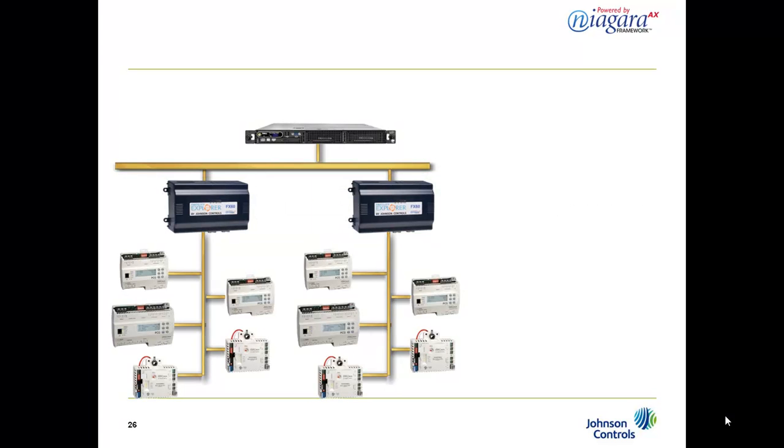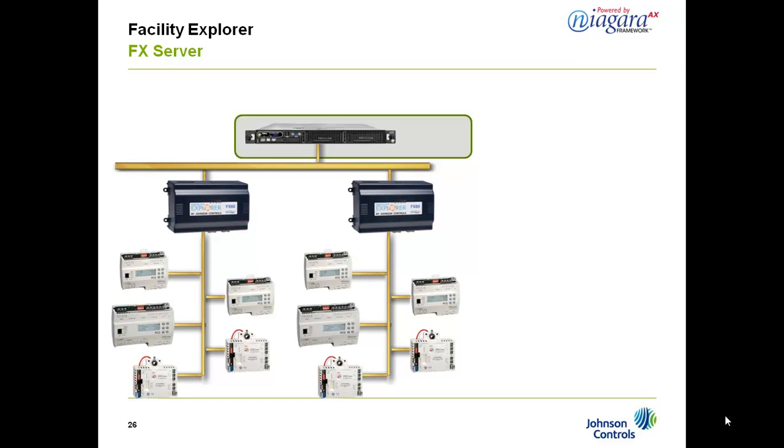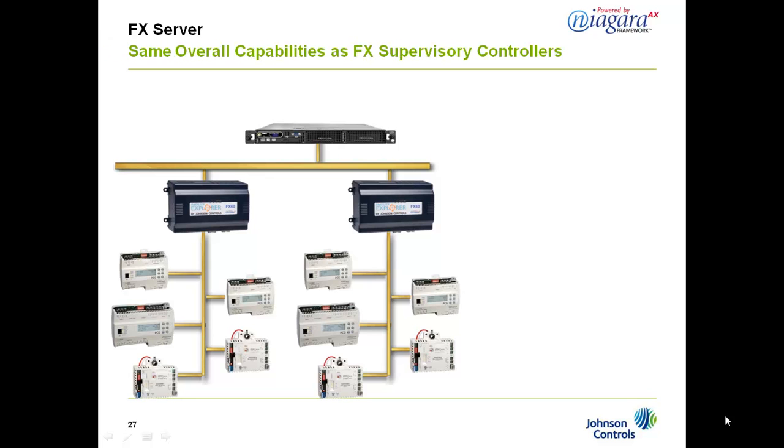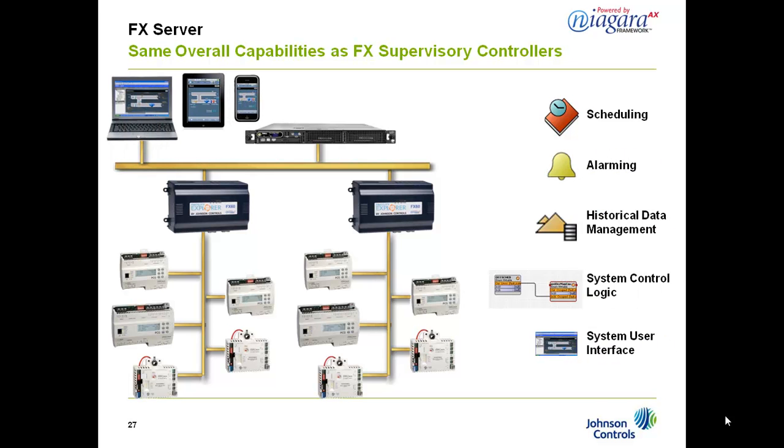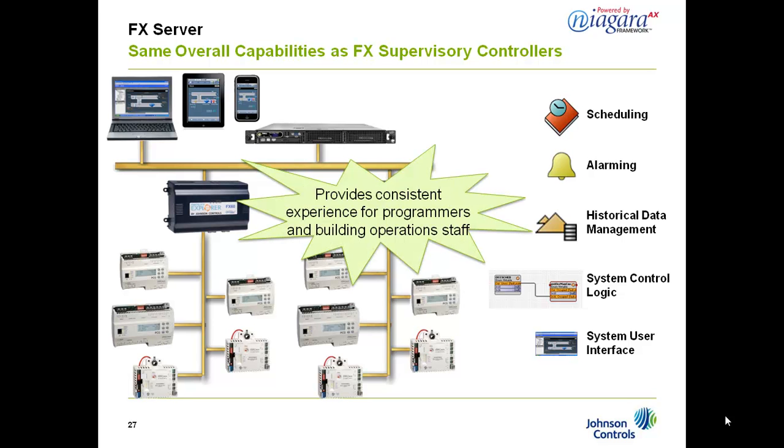The top tier of the Facility Explorer system topology is FX Server, which is an optional component. FX Server is also powered by the Niagara framework, and it's a licensed software product that is installed on your choice of hardware hosting platform, like a Windows PC or server. FX Server offers nearly the same set of control features and services as the FX supervisory controllers, including scheduling, alarming, historical data management, system-wide control logic, and serving up the system user interface, and it is engineered and configured with the same FX Workbench tool.